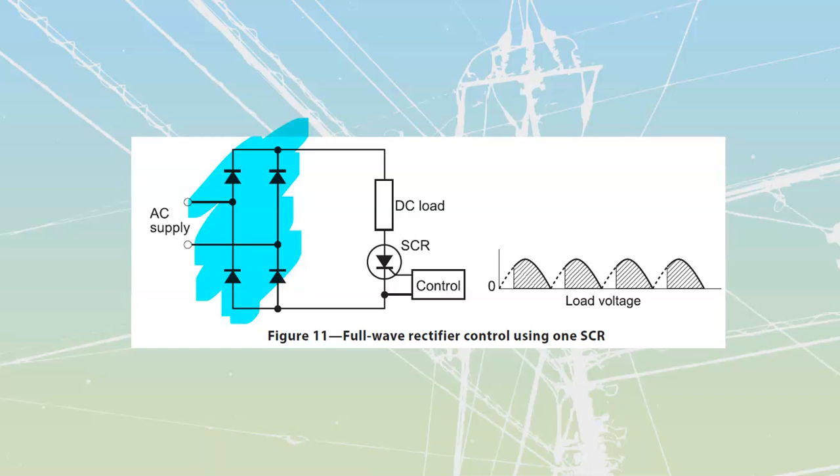Which ones of these are going to be my positive and negative? Well, I'm just going to take a look at this. If this is positive right now, I'm going to see which one passes. Will the positive pass to the cathode? Absolutely not. Will the positive pass to the anode? Absolutely. So this top bar over here must be my positive. And then if I change that now to a negative, I'll take a look. Will a negative pass through there? Nope. Would a negative pass through here? Yep. Therefore, the bottom would be my negative of this.